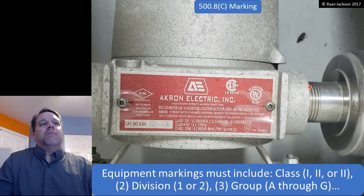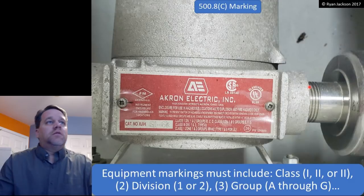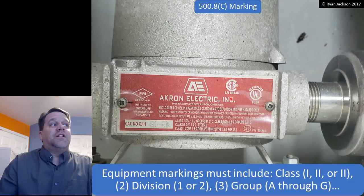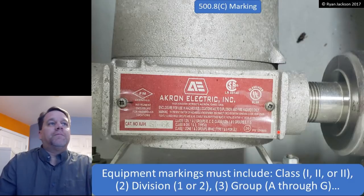Equipment markings must include the class 1, 2, or 3, the division, Division 1 or 2, and the group rating, A, B, C, D, E, F, or G. So Class 1, Division 1 and Division 2, Groups B, C, and D. So again, boy, if you're in an area that's hazardous due to acetylene, not a lot of options for you. Class 3, Divisions 1 and 2, there you go.